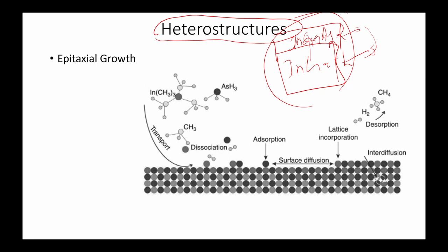Now, a heterostructure is not that easy with an elemental semiconductor, because the band gap of indium gallium arsenide is different from indium arsenide. Not gallium actually, indium arsenide, because indium gallium is not a semiconductor; indium and gallium lie in the same group. So indium gallium arsenide and indium arsenide are two different semiconductors which form a heterostructure.